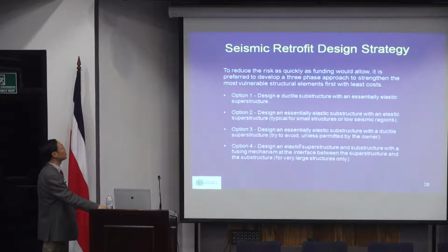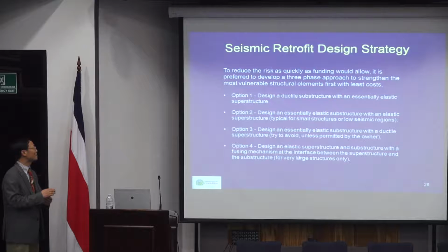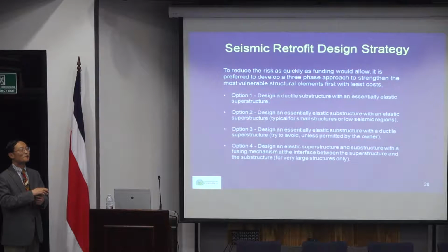And if you have really big bridges, you may introduce a fuse mechanism. In other words, the earthquake load does not exceed my design value. Once it exceeds the design value, which is an extreme condition, then that fuse will break, so that you will not be able to exceed that capacity. That is a more controlled way than a normal plastic hinge. A normal plastic hinge is something that you can estimate, but this is more manufactured.